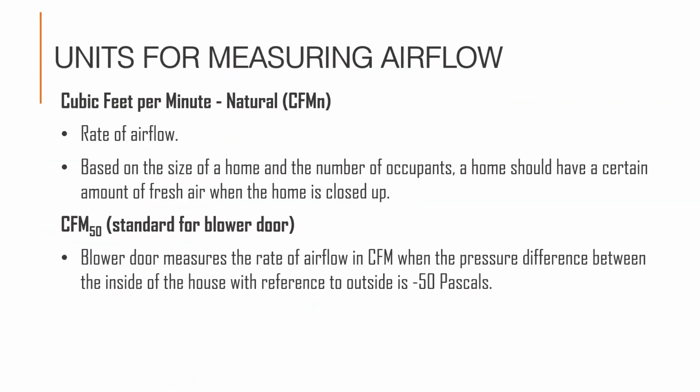Terms that we use to communicate measurement of airflow include cubic feet per minute natural, or CFM-N, to represent normal conditions, and CFM-50 to represent airflow measured with the blower door running. CFM-50 is how we communicate the blower door test results.